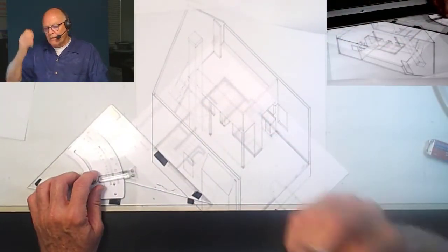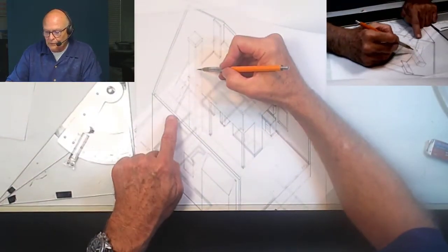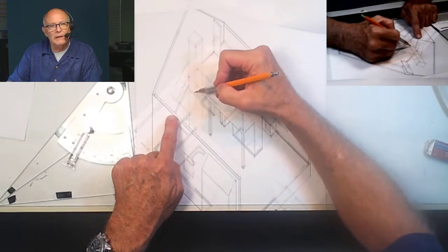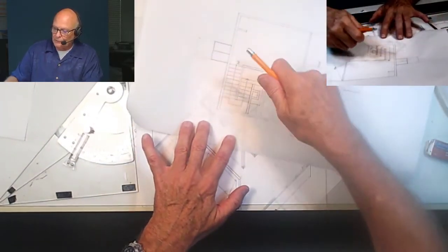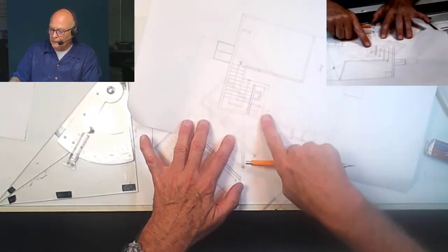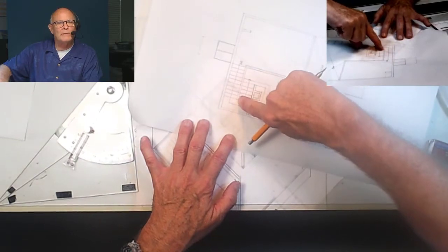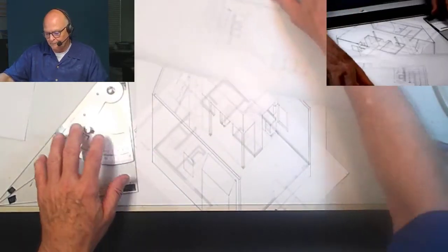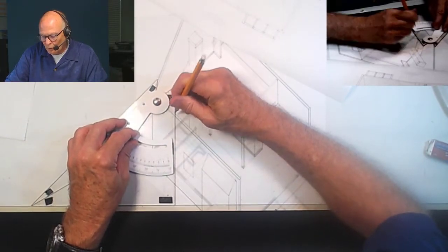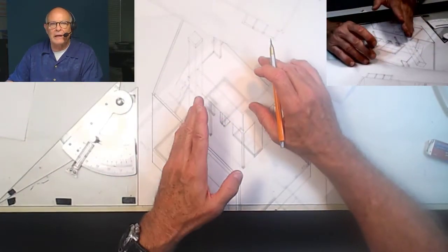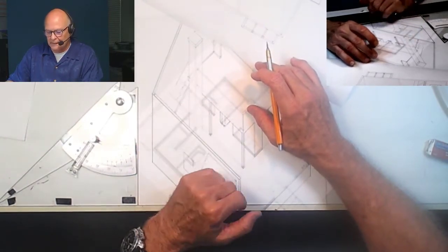There we go. That's the end of that stair railing. It starts up here, goes behind the chimney here, and extends down to the end wall. So it's coming out here. That chimney is in front of it right here from our view orientation. It breaks out and it stops right there, and then it drops vertically. Okay, so that represents that wall. Now, it's not the same as the back wall of the fireplace. We'll look at that in a minute.